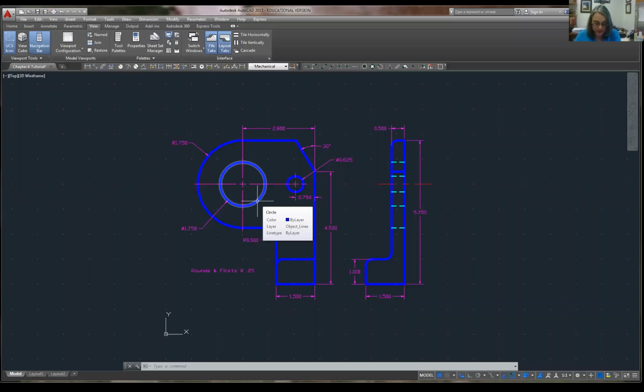So we're going to use the basic hole system. Basic size is 1.75. That will be the minimum. Our maximum will be 1.75 plus 0.0025 or 1.7525 inches. And I'm reading this actually from page 25 in your text.